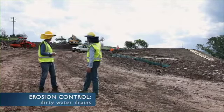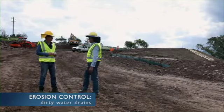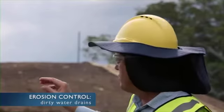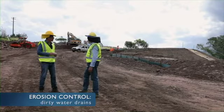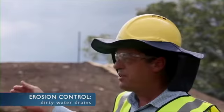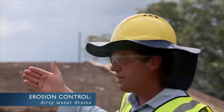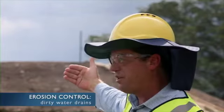How we're managing it is we've actually got sediment basins here that run along the side at the base of this actual cut. So that's our end-of-line control. But as you can see, it's really actively worked. We've got trucks running up and down there all the time. So what we need to do is actually have a responsive measure here, and we need to put in responsive techniques like cut-off drains, which will get that dirty water to the controls on the side.